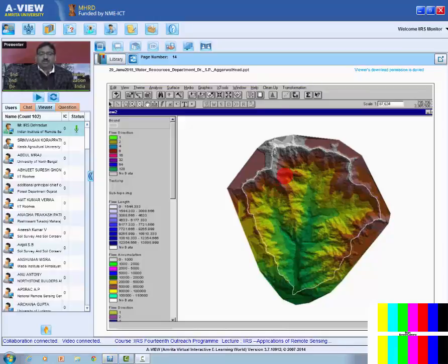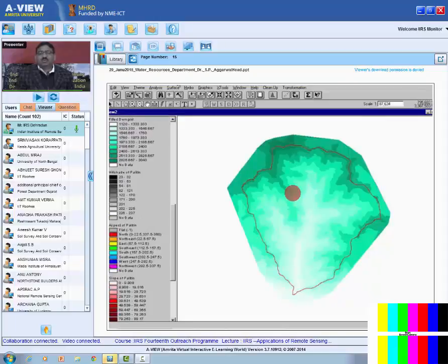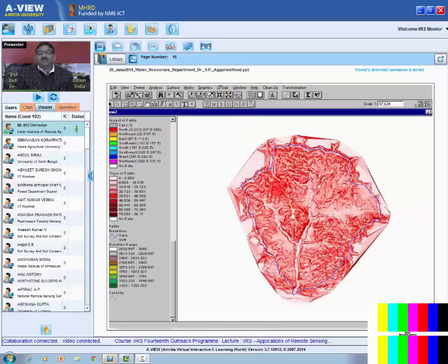Now after that, so this is one parameter, a topographic parameter. We will start one by one. So we have this watershed DEM, so I can have a nice gridded DEM from it. Then the next step is I can have a slope map. Now for this, either you can use ArcView or you can use ArcGIS. There is an option in ArcGIS, ArcHydro. You can go and calculate all these things. So you will get the slope map of your watershed.